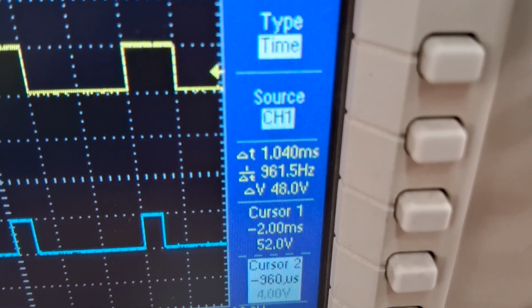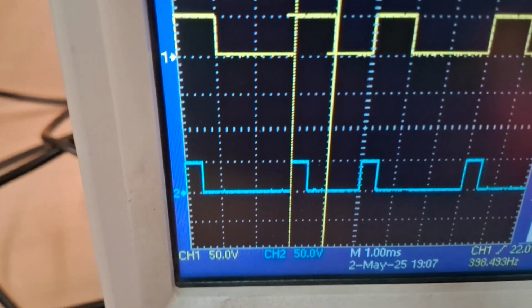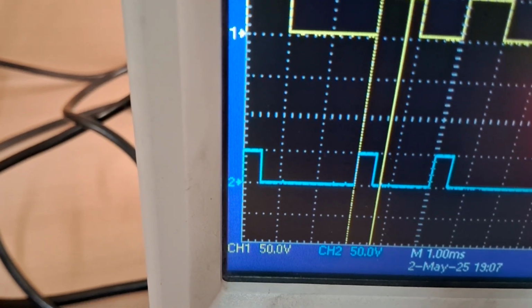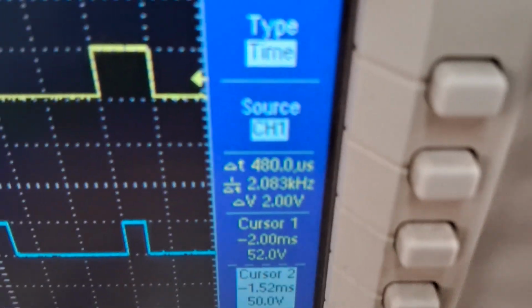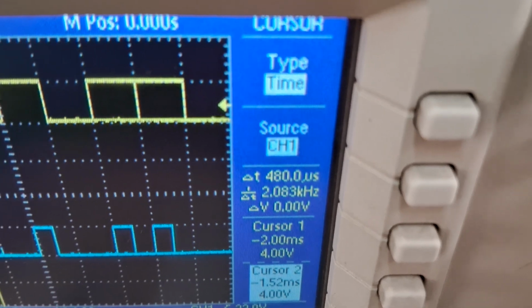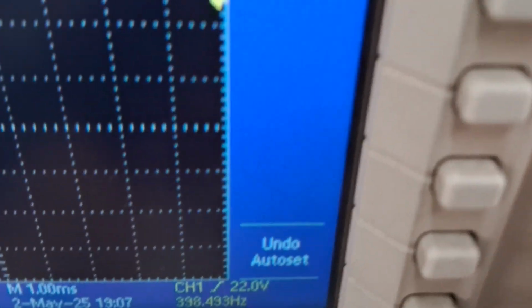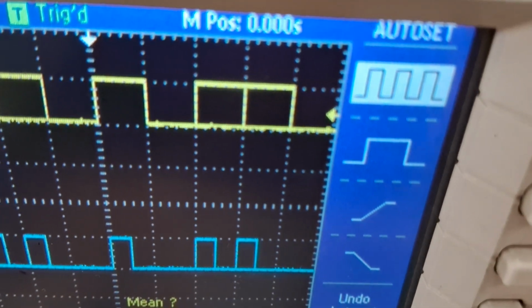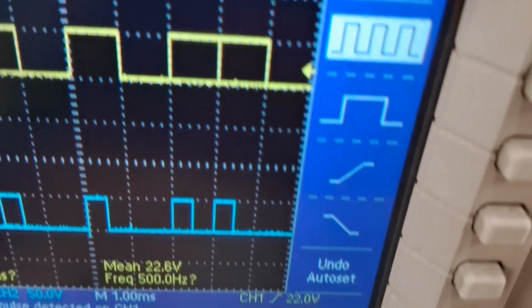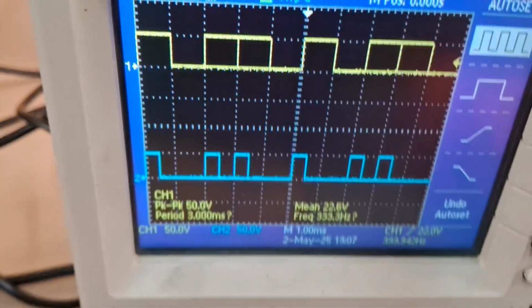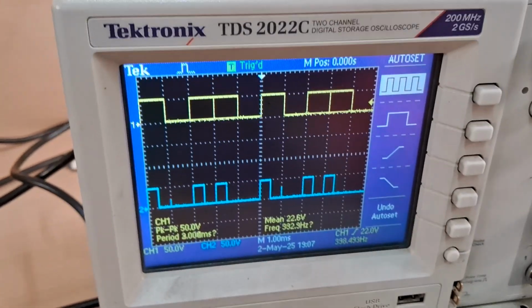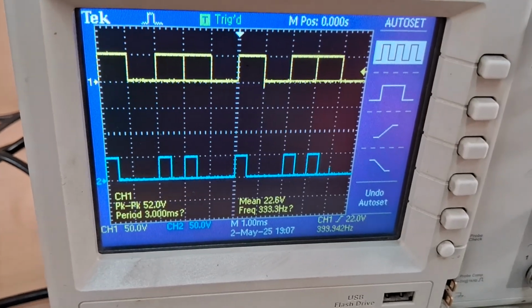Now I need to measure the duration of the return to 0 format, that is unipolar return to 0 format. I'll bring the cursor over here. Now what you can see is it is 500 microseconds. Once again we'll just move it and we'll say 480 microseconds, corresponding to 500 microseconds, that is 0.5 milliseconds, which you can observe. So it's exactly correct.